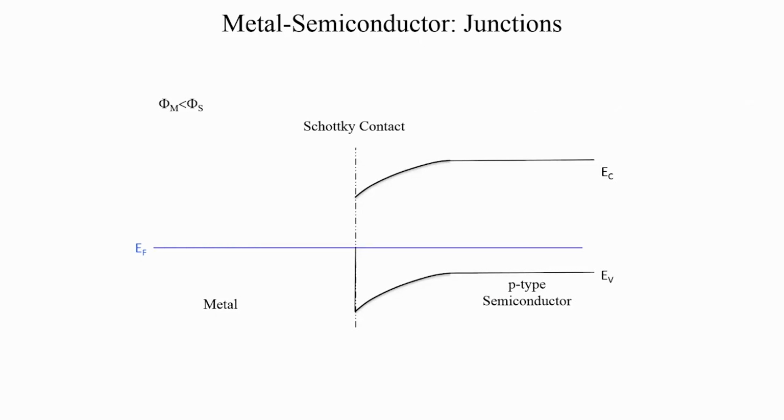You have the Fermi levels that are aligned deep in the bulk, there is nothing interesting, it is still your regular p-type material, but at the interface the semiconductor has increased its electron population, and you find that the conduction band bends towards the Fermi level because of this increased electron count. But then what kind of a contact is this? Since holes are the majority carriers, let us look at what the holes experience. The holes now see a barrier, they have to run down the hill.